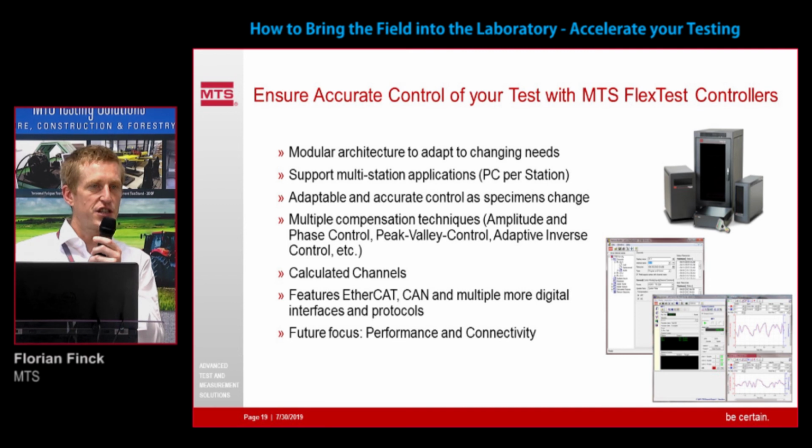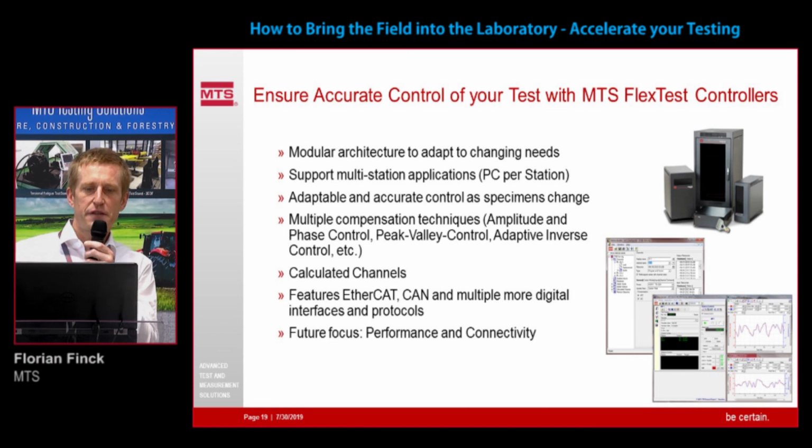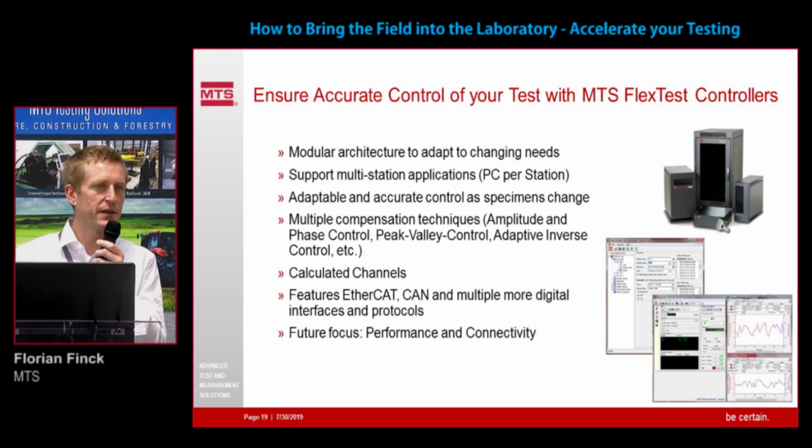We have calculated channels, so you can make use of different information from sensors and calculate channels that you use for the evaluation of your test. And then we are featuring EtherCAT, a digital interface to help you talk to the vehicle bus. There are gateways to talk to FlexRay.